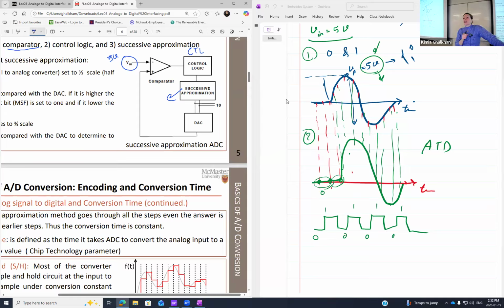That's exactly the same register, CTL. CTL adjustment, yes, it is your job as an engineer to adjust it based on the application. But in reality, you are going to adjust the information of the CTL register inside the microcontroller, but you are not generating information in there. You just get access to that register inside the header file.